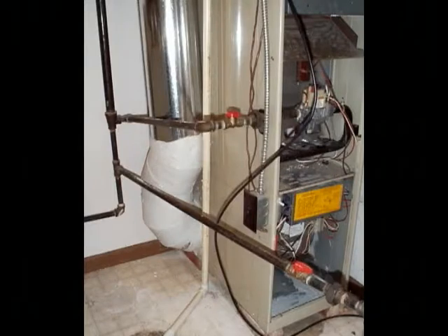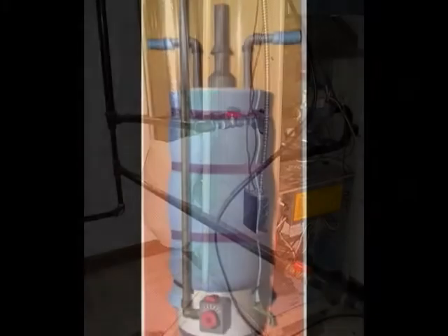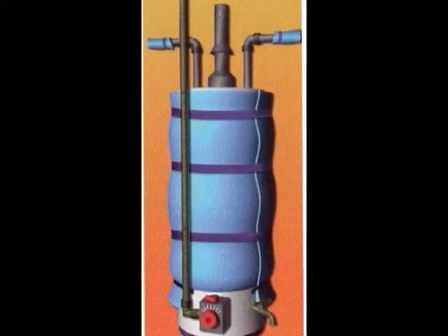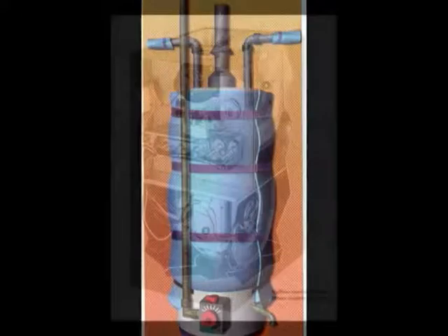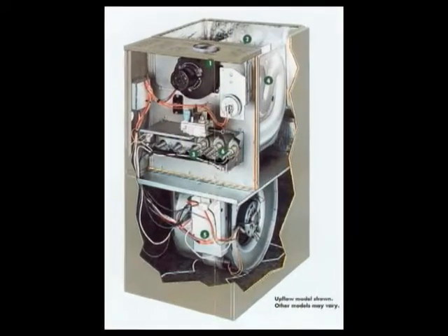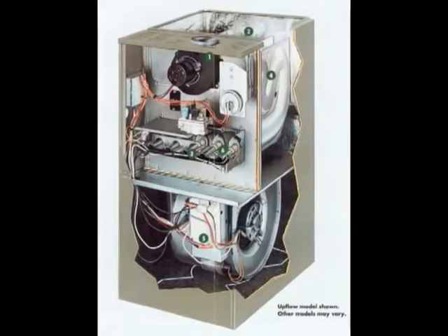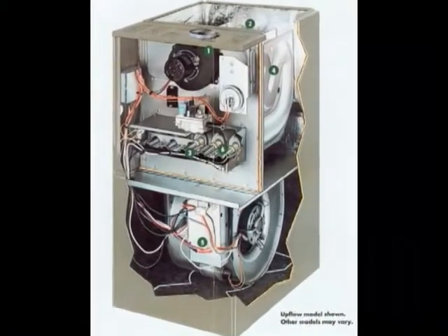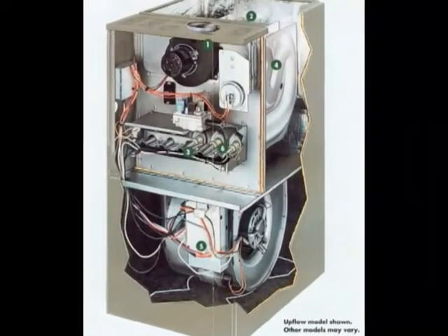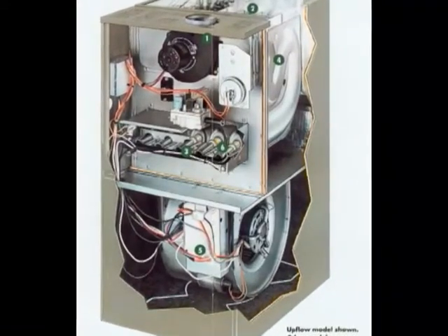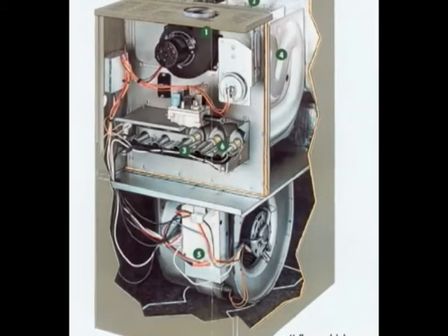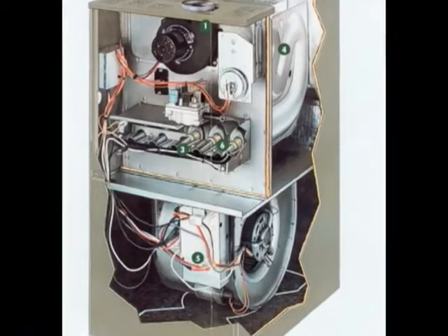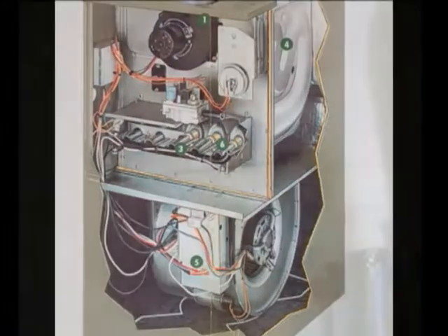Of all the Category 1 appliances, the most susceptible to spillage, backdrafting, and flame rollout are natural gas or propane furnaces, water heaters, or boilers which have draft hoods or dilution air ports that are open to the CAZ. Newer mid-efficiency gas furnaces, as mentioned earlier, usually have pressure sensors that lock out the system if a positive backdrafting occurs. While safety is usually maintained, it does create what may be misinterpreted as an unexplainable nuisance trip.